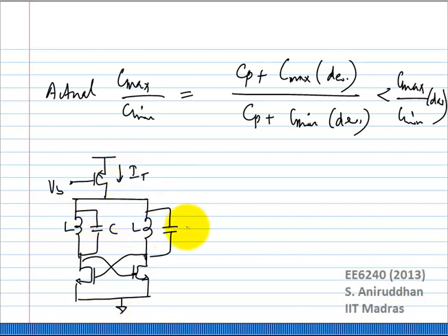I can very well choose to take the NMOS cross-coupled pair oscillator and drive it with the PMOS current source. What is the difference between the two cases? Obviously, the output common mode is going to be different, right? That is a given. Anything else? Parasitics will increase.